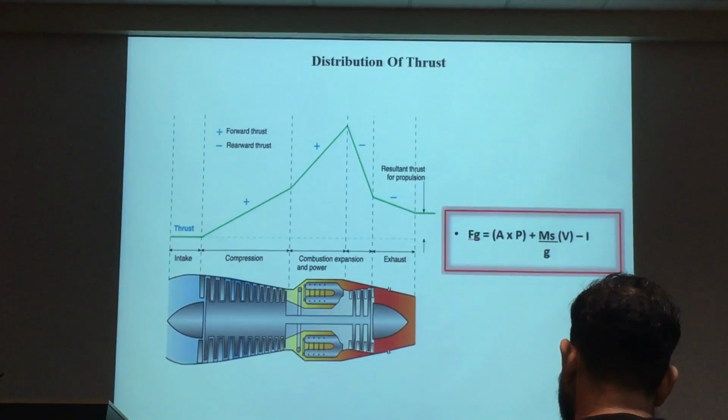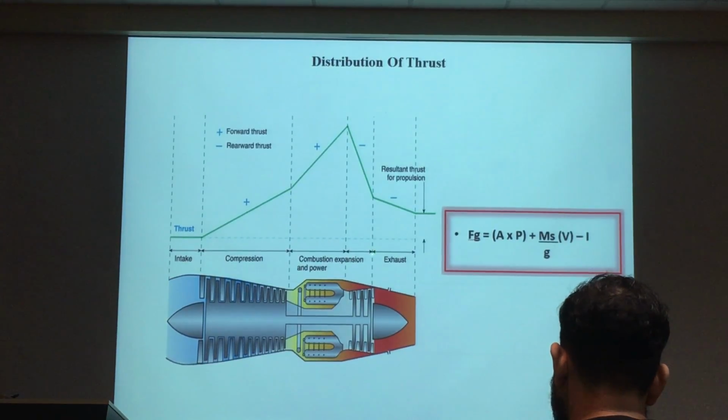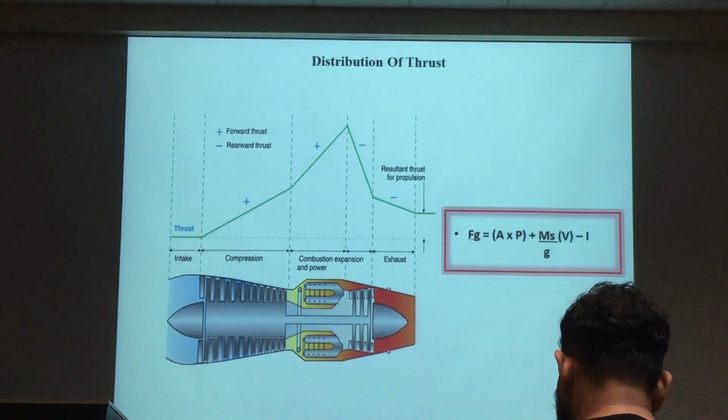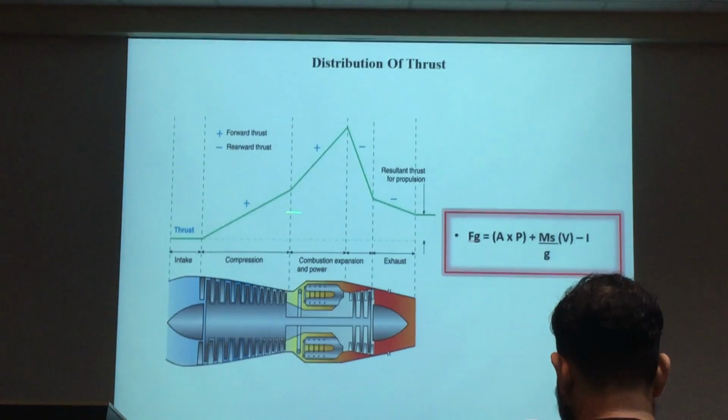Okay, this is what you're going to get, the FG. The FG is down here. Now you take the turbine exhaust here, outlet. The turbine inlet is the highest. Remember the nozzle guide vane, I give you the highest potential thrust energy. You minus all, you're going to see your value is minus. The FG is minus. Okay, this indicates to you the turbine is a negative thrust. You don't produce thrust, actually you take out energy. You make the thrust lesser. That's why you call it negative thrust. You practice your computation number 1B, you understand all this formula. Clear?